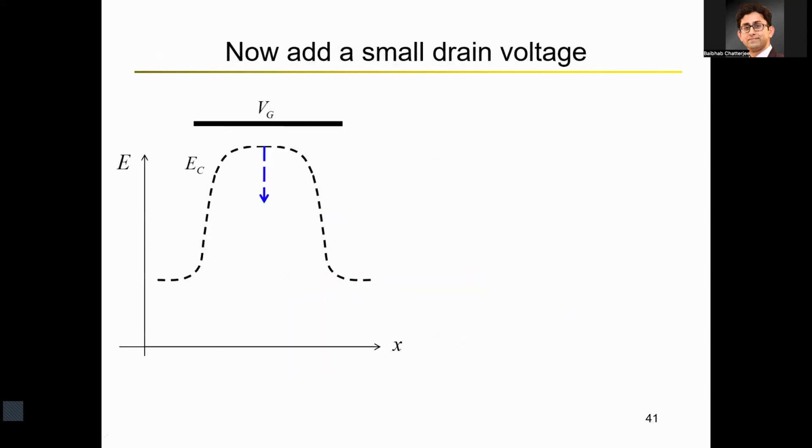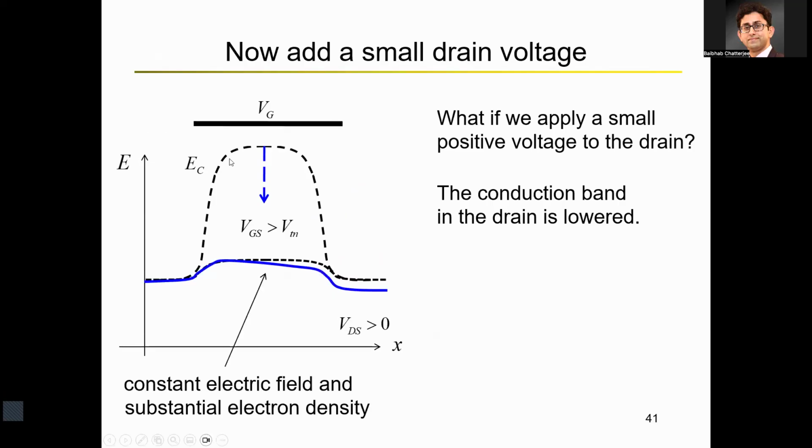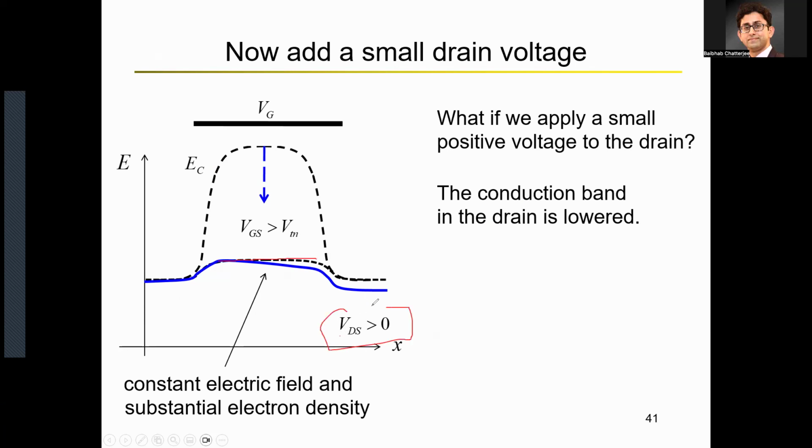All right. Now, as you apply a positive gate voltage, you're reducing the barrier height. But if the left side is at the same voltage as the right side, so let's say you have VDS equal to 0, and if I go back one slide, you had this flat barrier. On the other hand, if you apply a drain to source voltage VDS greater than 0, remember again, this side is source, this is the channel in between, and this side you have drain.